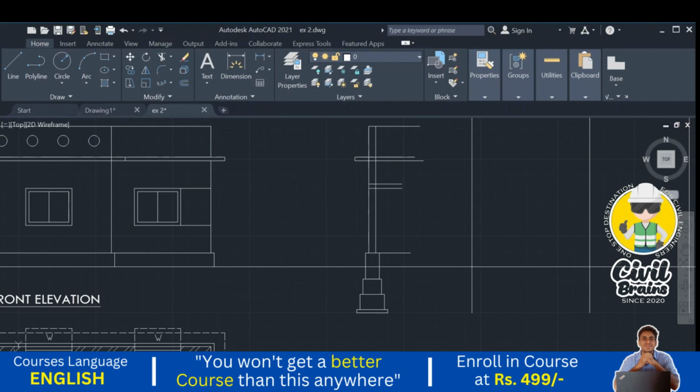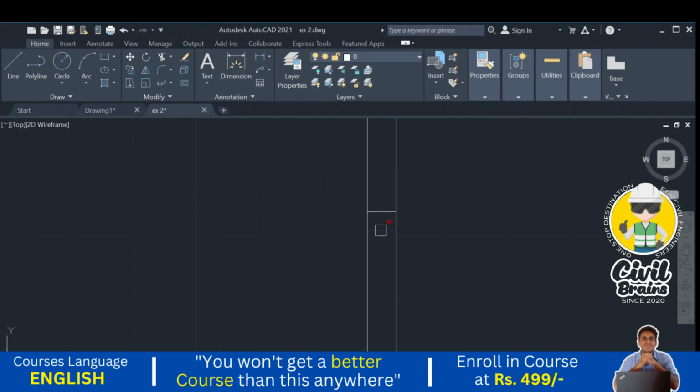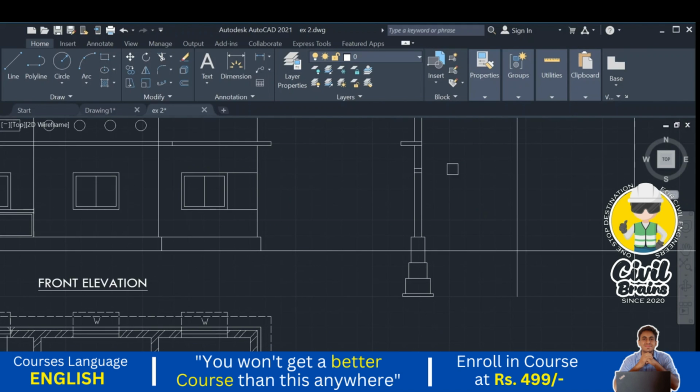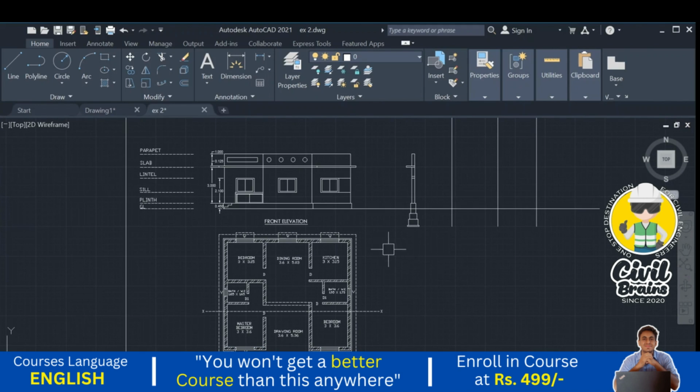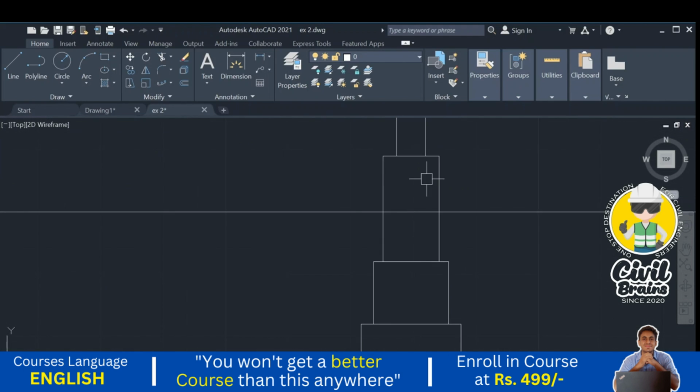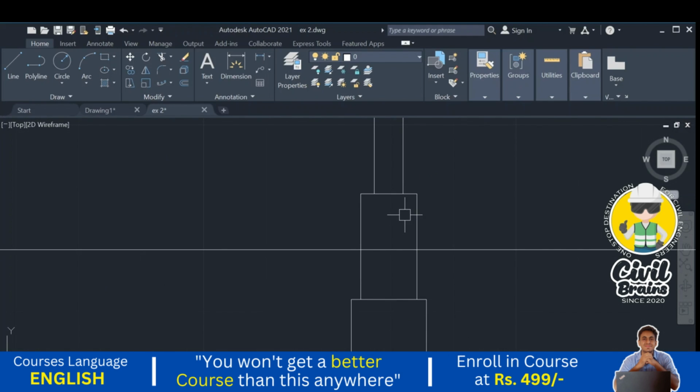Okay, so I just delete these extra parts. Okay, this is our lintel, this is our slab. Okay, so now I do just one thing here. So one section I have drawn. Okay, here I need to provide the PCC also. At the plinth level we need to provide the PCC also, so as to avoid dampness in the floor.